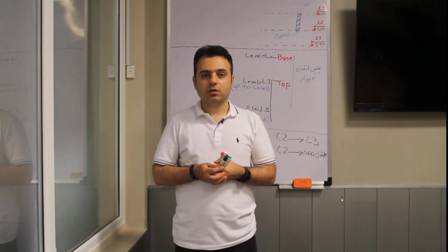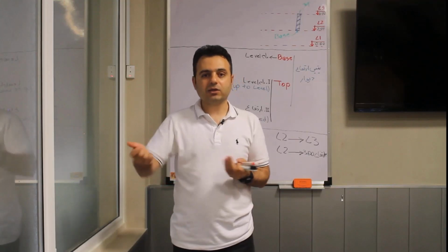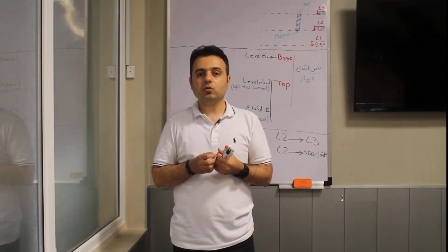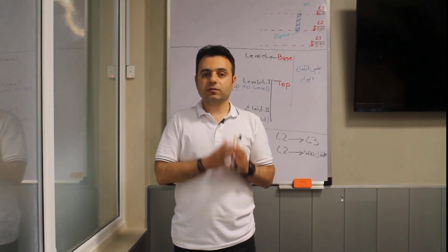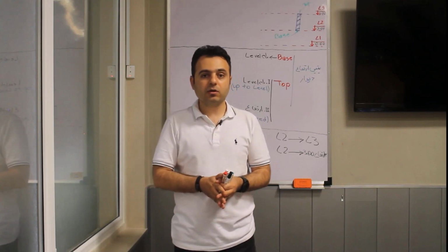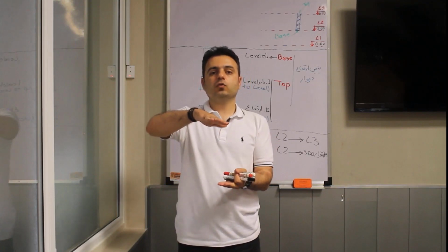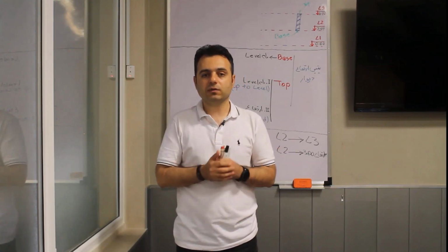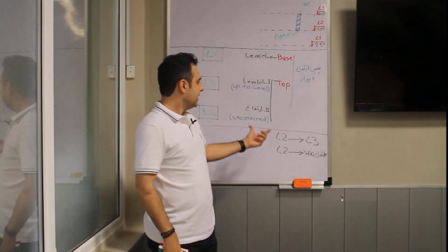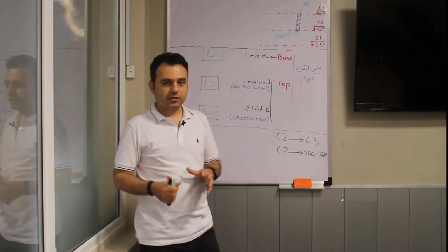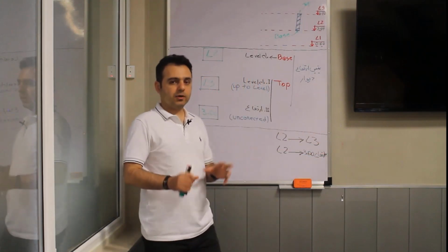What other examples do you know for unconnected? Well, for example, the partitions or the walls of the yard. For example, the walls around the garden. If you pay attention, these walls are not always short. For example, the walls of a yard might actually be too tall, but not connected to the height of the floors. For example, you go and buy a partition from a company whose height is 220. Well, we give it a height and then it's over. So while we are drawing walls whose height is not related or connected to the height of a floor, we use the unconnected method.